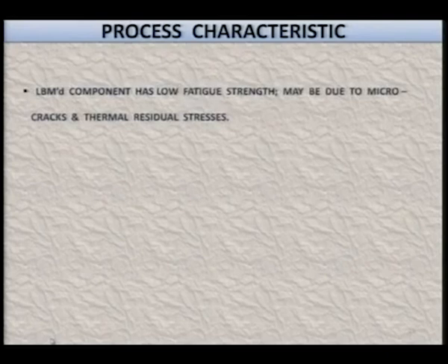Laser beam machined components have low fatigue strength. It may be due to micro cracks and thermal residual stresses. I have already shown in one of the figures that micro cracks are developed during laser beam machining, and because it is a thermal process, high heat energy is produced at the workpiece beam interface. As a result, you end up with the component having thermal residual stresses. Both these factors add to the reduced fatigue strength of the laser beam machined component.